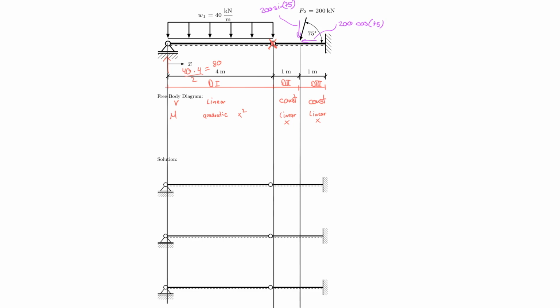All right, so on the left side, I have a roller. Now we're talking about the normal force diagram, and normal force here happens to be in kilonewton. On the left side, I have a roller. That means the normal force cannot be resisted or created, so everything here has to be equal to 0. So I'm going to indicate that by a line through there.